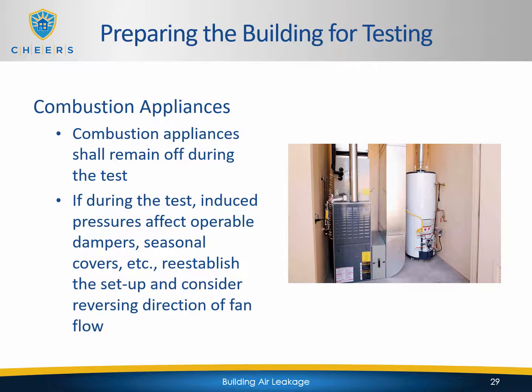Combustion appliances shall remain off during the test. If during the test induced pressures affect operable dampers, seasonal covers, etc., reestablish the setup and consider reversing the direction of the fan flow. It's very important that combustion appliances stay off or on pilot during this test because you will be depressurizing the house.